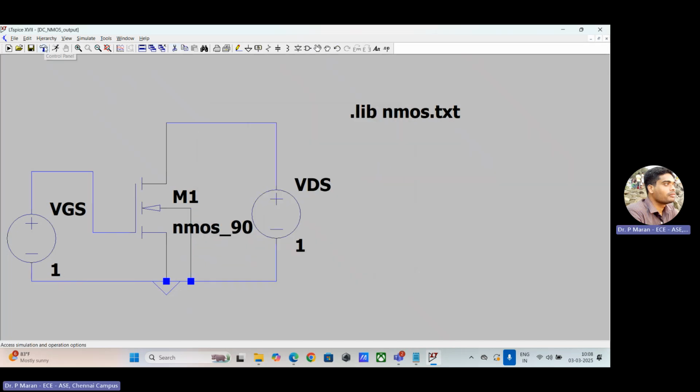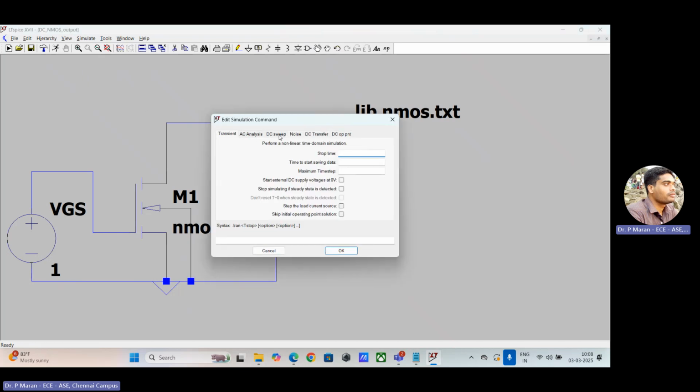Okay, I will start from scratch. Other things are the same. Do you follow me or not? Just I have to change the simulation command alone. Go to Simulate, Edit Simulation Command, and I am going to do only DC simulation now.